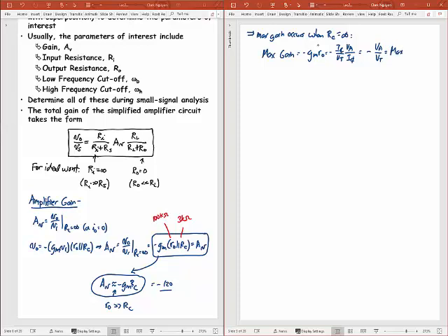That means the maximum gain, if you could send R sub C to infinity, ends up being dependent not on your circuit at all, not on the R's that you put around your transistor at all, but on the physics, on what the early voltage is divided by the thermal voltage. That's the best you can get out of this transistor. Okay? Always a good thing to do, to figure out what your maximum is. All right, so we have part of this problem done.